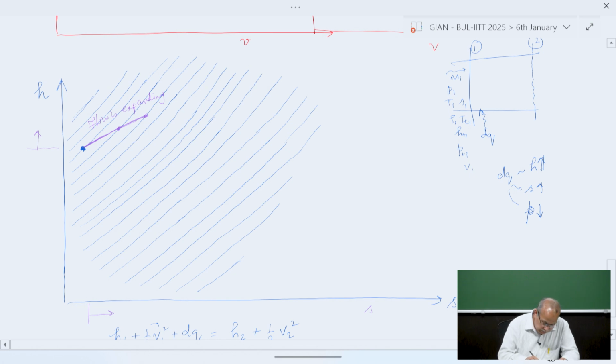Again, you see this is continuing to increase. So in this direction, the addition of heat will cause the flow to decelerate. Sorry, the flow to accelerate. The flow is going through a decrease in pressure, the flow is accelerating here. And then this continues